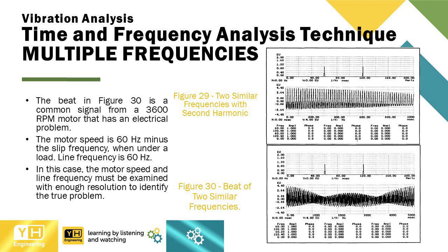The motor speed is 60 Hz minus the slip frequency, when under a load. Line frequency is 60 Hz. In this case, the motor speed and line frequency must be examined with enough resolution to identify the true problem.